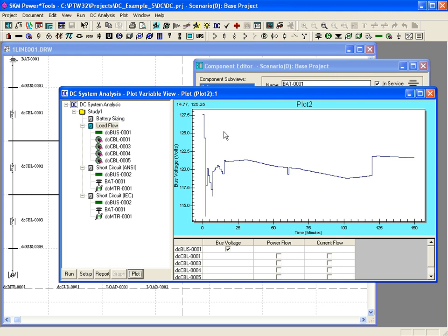At first glance, the plot looks like there are wide voltage swings, but a check of the voltage scale shows that the voltage swing is not as big as it looks at first glance. During most of the discharge, a NiCad battery provides about 1.2 volts per cell. Thus, with our 100-cell battery, the battery voltage is approximately 120 volts, except for periods of high discharge current.